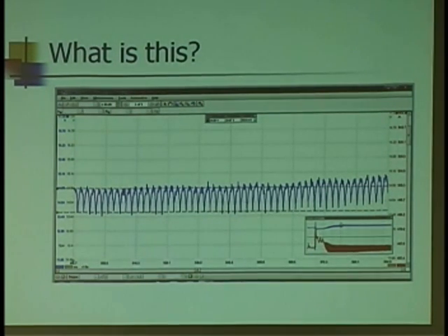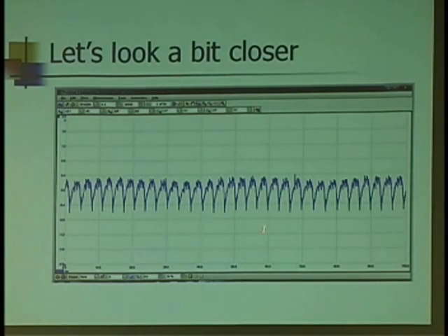The other thing, I don't know if you can see in your pattern, remember I showed you on the good pattern, there were nice, round, even humps. When you see a bad one, I still see those nice round even humps, but they're embedded in the bigger peaks. Do you see that? So it's almost as if I had, or like a relative compression exam. I've got 4 or 5 good ones, and then whoop, nobody home. So in this case, one diode is not doing its share of the work.